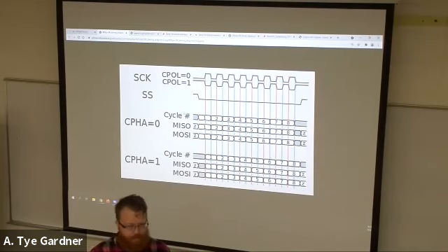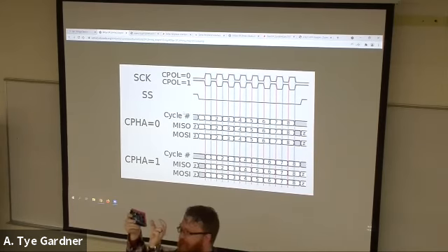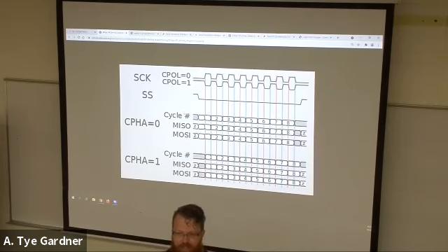If you remember your boards, it is going to plug into one of these little connectors on the end. So it's a little adaptive module, a little handout that just plugs in right there and expands the capabilities of this board. Make sure that you understand the constraints file so that you can map these pins with what's going on inside the FPGA, right? That constraints file tells where this is physically versus logically inside the FPGA. That's how they communicate.